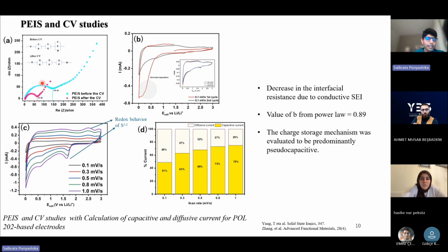After doing an impedance study, that is PEIS, before CV, you run a CV experiment, because in the CV experiment you are actually forming an SEI. As I was saying, SEI will be inherent in every battery, irrespective of whatever material you have on top of the anode.